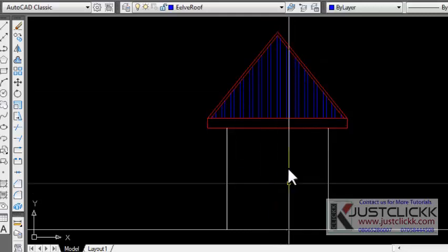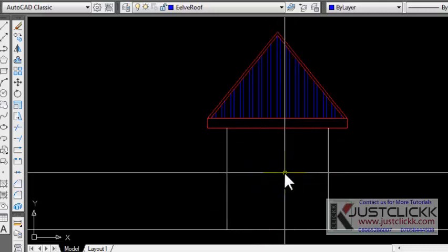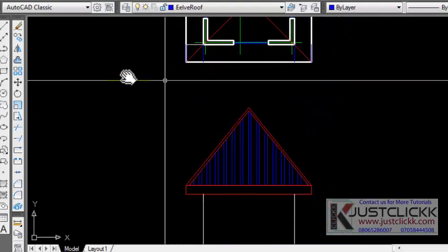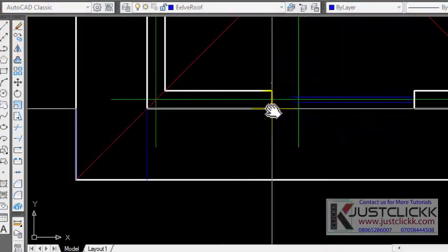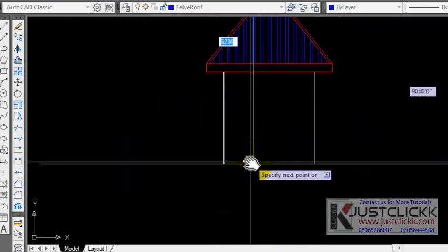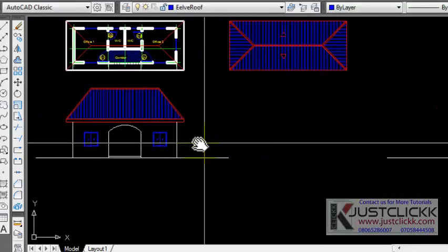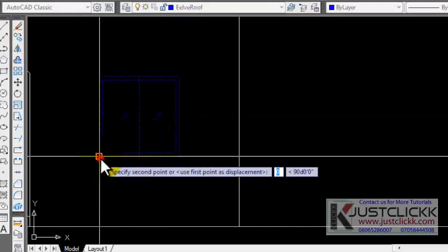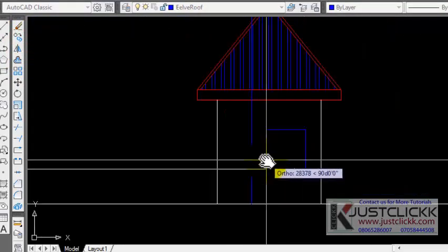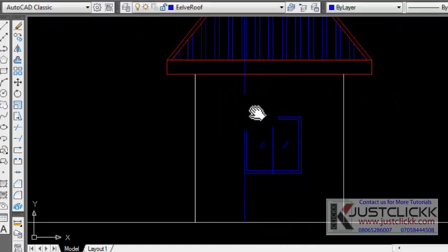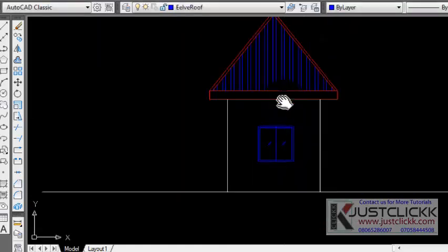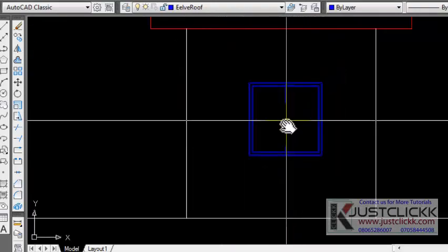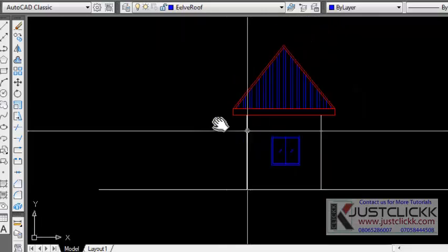There are no windows here, there is no door here, so this is how blank the wall is. Let's see. Oh, sorry, there is a window. We have to track that down. Just come here, pick this, track it down to this portion, or rather you can copy this window here. That's why we're using a computer. Copy this window straight to this place where you have tracked down, and that's all. It solves the problem. It's the same window size, so there should be no fear. This is 1200 and that window is 1200, so that takes care of the whole lot of issues here.